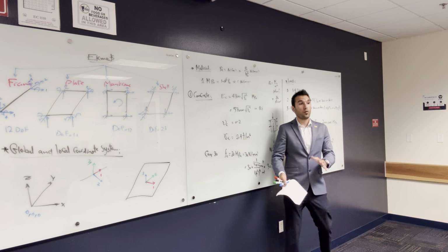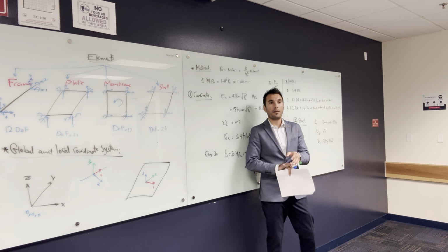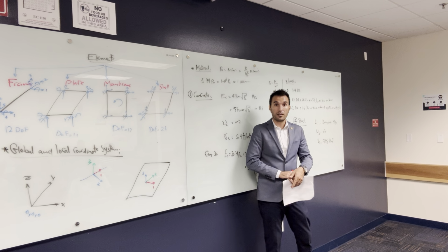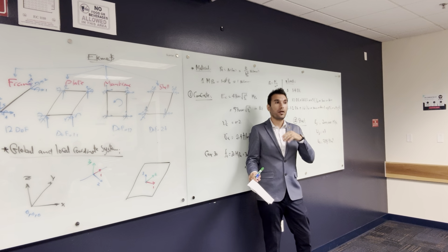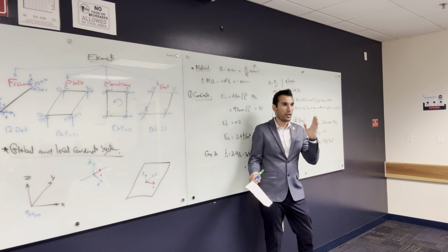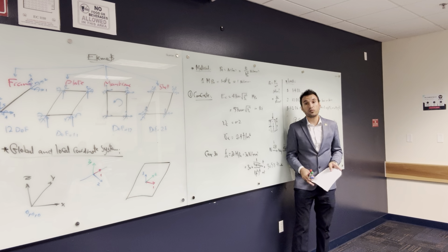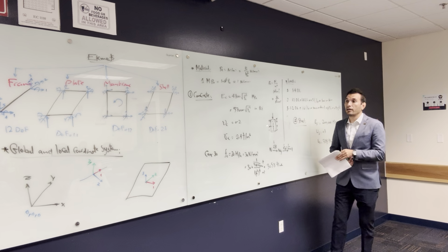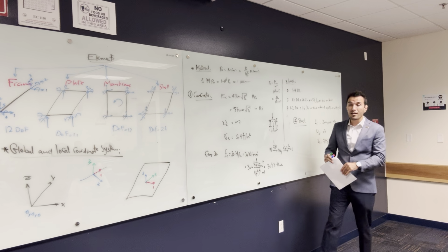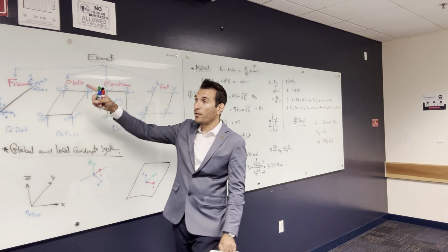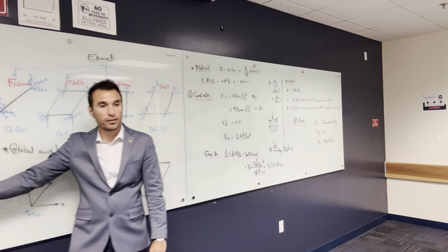Because when you have a tall building, it is not just a building that you design and we are done. We do value engineering, we do economic analysis, we have to reduce the amount of reinforcement, we have to reduce many things, because if you save, I don't know, $100,000 in one story, and you have 50 stories, you save $5,000,000. So it's really important that we understand the different components when we do structure analysis using software. Mainly in any software, it is the system: you define the material, you draw the geometry, define and assign the loads, run the analysis, and then visualize the results.